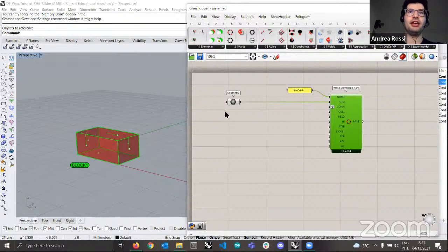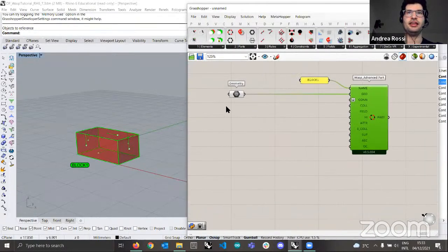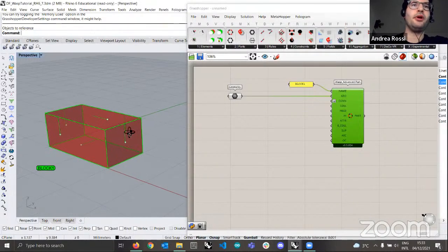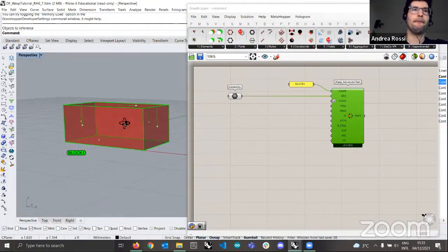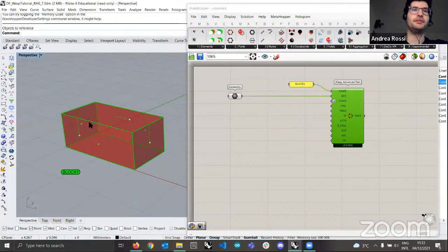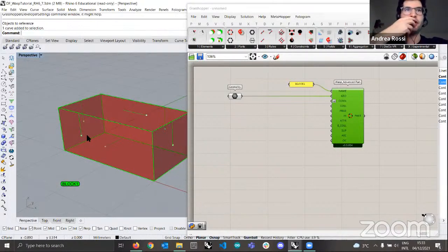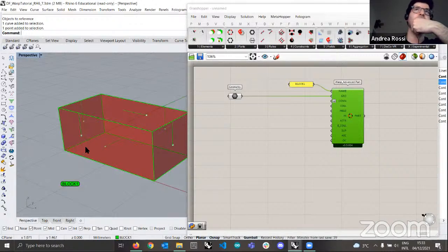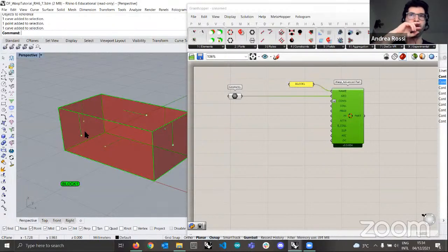Now the last thing we have to do is specify the connections. You'll see that on our block here, we have a series of points and a series of straight lines. This is the information that we're going to use to create our connection. The reason we need that is that if you just specify a point, it gives you information about a position where 2 elements need to connect, but it doesn't tell you anything about the orientation, because they could be connected at any angle. That is why we create this second line, which allows you to specify not only the point, but also the exact position where that is.